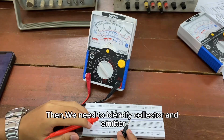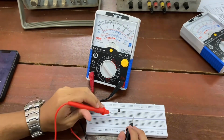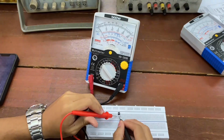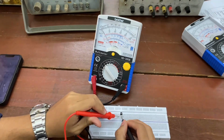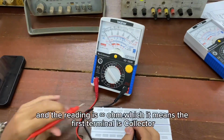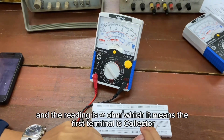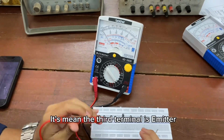Then, we need to identify collector and emitter. Put the red probe to the first terminal and black probe to the second terminal. And the reading is infinity ohm, which means the first terminal is collector and the third terminal is emitter.